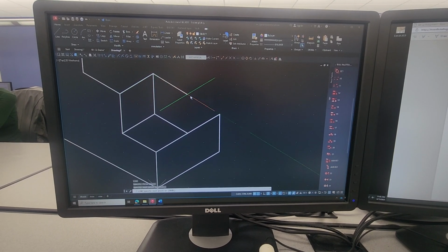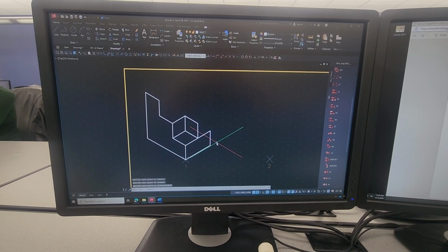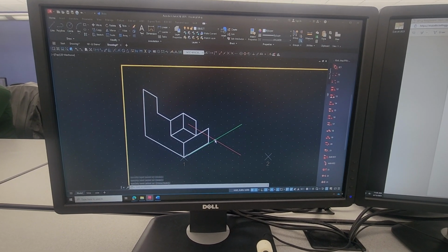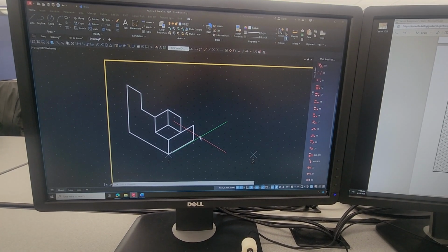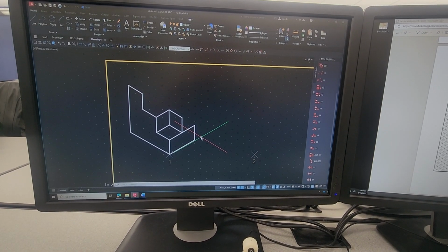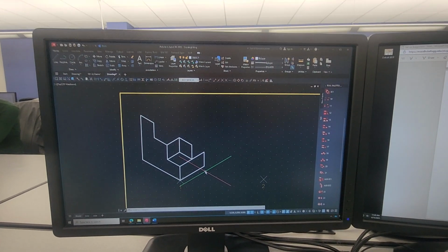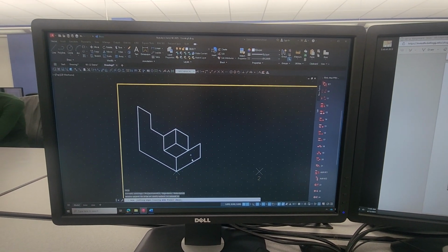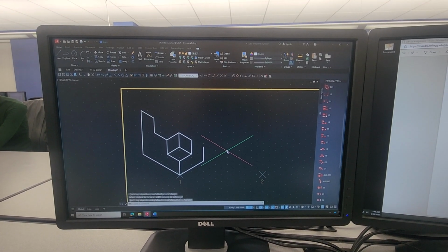Yes, Brody? So it's kind of similar to 3D Sketch in SolidWorks, right? Kind of like it, okay? But not in reality. We don't have to worry about origins here, okay? It won't actually dimension it for us either, okay? So we say roughly and loosely, yeah, you're right. But in this case, I would never have equivocated it that way. But again, watch out and make sure you're not drawing things you don't need to, as I just did with that line right there. But that's how we get the 3-dimensionality of these things.